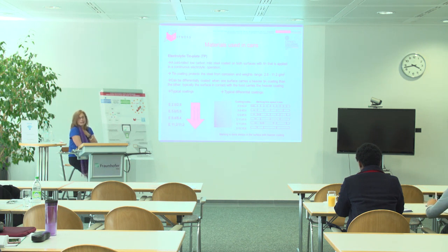Okay, I select the tin coating weight according to the corrosion protection I need. If I need a high level of protection, I select a high weight tin coating, like 11 or something like that. But if I don't need a high level of protection, I can use low levels of tin.